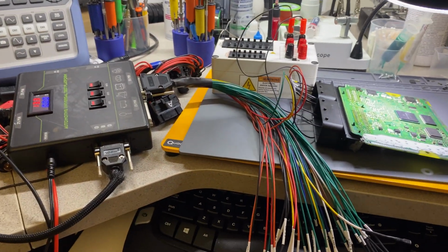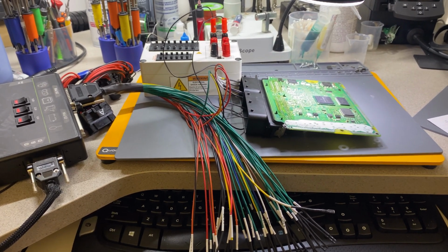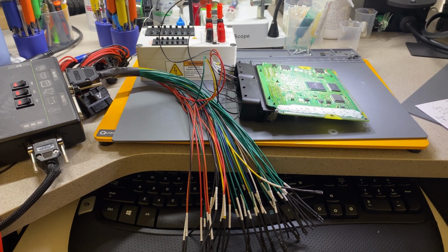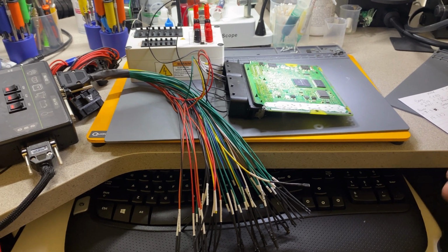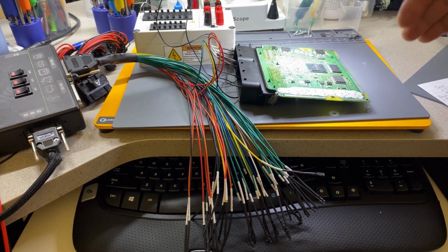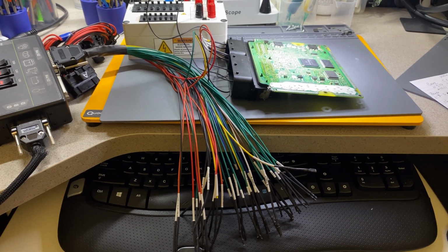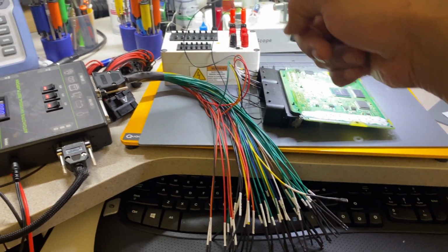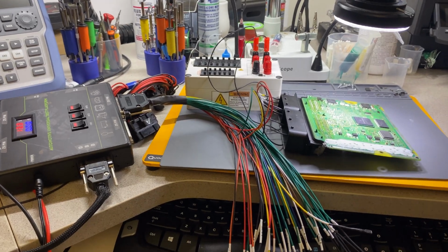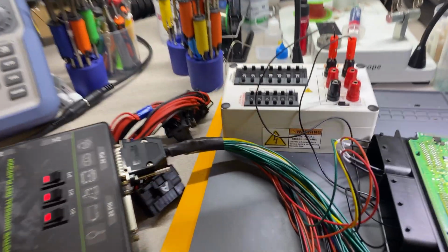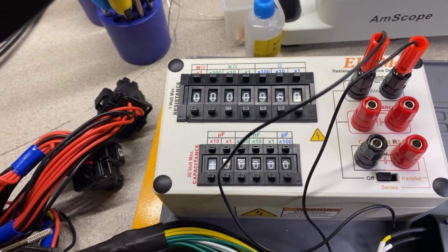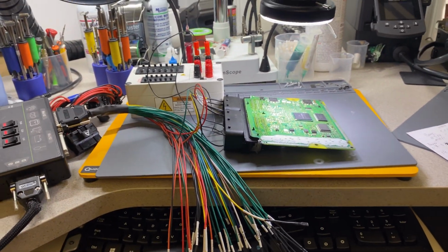So this is a quick way of how I test the computers. After that, if I have another issue with the computer, then I go there specifically. Let's say no throttle, no O2 sensor, or no coolant temperature sensor, and then I follow that circuit itself to provide the simulation like I have right here ready to do a test. Let's say the fuel temperature sensor or the coolant temperature sensor, I just use a decade box. This one can provide resistance and capacitance, or both together, depending on what you're trying to test, and it worked really good.